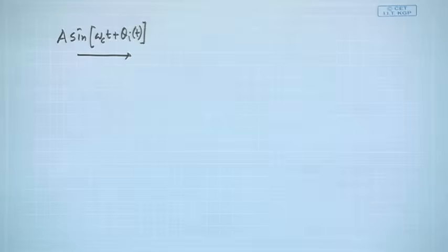So, basically, before the PLL you will always employ that squaring circuit, and for SSB and VSB we have said that the PLL cannot even work because squaring does not give me the carrier. If I do not get a pure carrier over here, the VCO cannot help. So, it is very important that after squaring and putting a narrow band pass filter, I must get a carrier. If I am getting that, then I can employ the VCO technique.